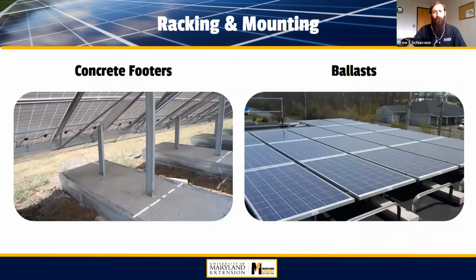Some other examples here: a concrete footer on the left. This is for a larger project. I don't know how many cubic yards of cement that is, but if you're using cement like that, it can add up quite a bit, and it's not so attractive economically anymore. So typically on a larger scale, utility scale projects especially, you'll see those piers or piles driven straight into the ground rather than such a substantial concrete footer.